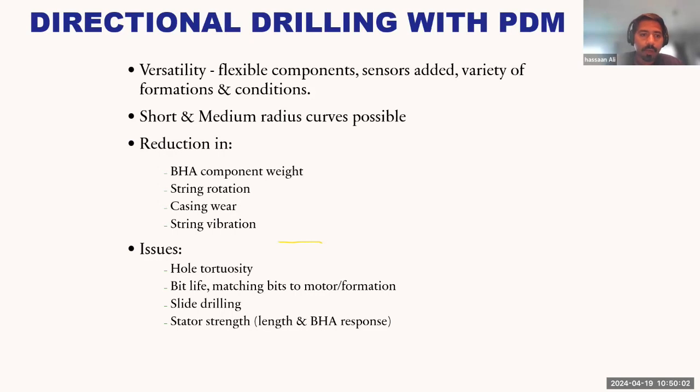You will be able to drill medium and short radius curves with the PDMs. Sometimes when you are trying to have a much bigger angle for the build-up section, then you might need a whipstock which is developed just for that angle. There is a range of radius that can be offered by the PDM.